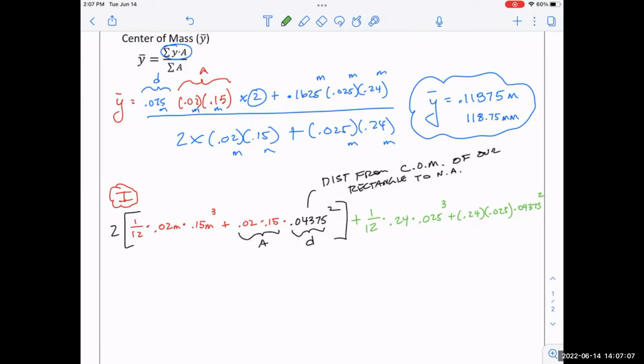But if I took the same exact material and I stole the material off the sides here and put it up on top, that would now have a larger I value. So I-beams have a better I value for the amount of wood that you have. That's why those engineered I-beams are so cool. If I just cut this part off, you can't glue it up on top. You're just throwing it away. Just cut it out of a tree, boom, there's your beam. It doesn't cost that much money to manufacture that. What they did out there, super complicated, but it's using the materials a little bit better.